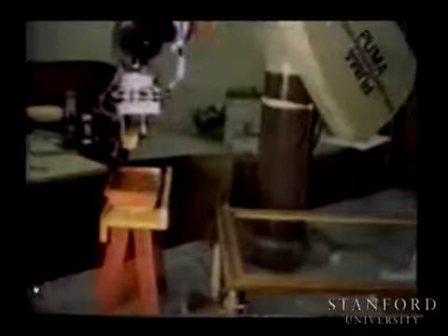So this video is about a very important aspect of robotics, which is compliant motion. You see the sponge is pushing up, and you see no deflection on the sponge, right? Which means that there is no force applied. Here we are coming to a surface that is unknown, and the robot is sliding over the surface. So it's making contact at different points. If even we remove the whole object, now here is a wavy surface that is being followed just by saying press down and move to the right, cleaning a window without breaking it. It's very important.